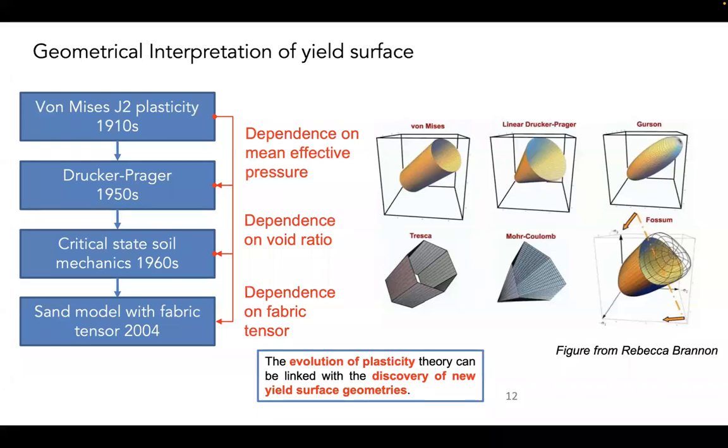The yield function is basically a specific way to represent a surface, and that surface is like the speeding ticket I talked about: a criterion to indicate some change. Different types of yield functions correspond to different physics. I will talk about them one by one, but long story short, I just want to point out the connection between creating a geometry and writing a yield function. So the yield function has a physical consequence.